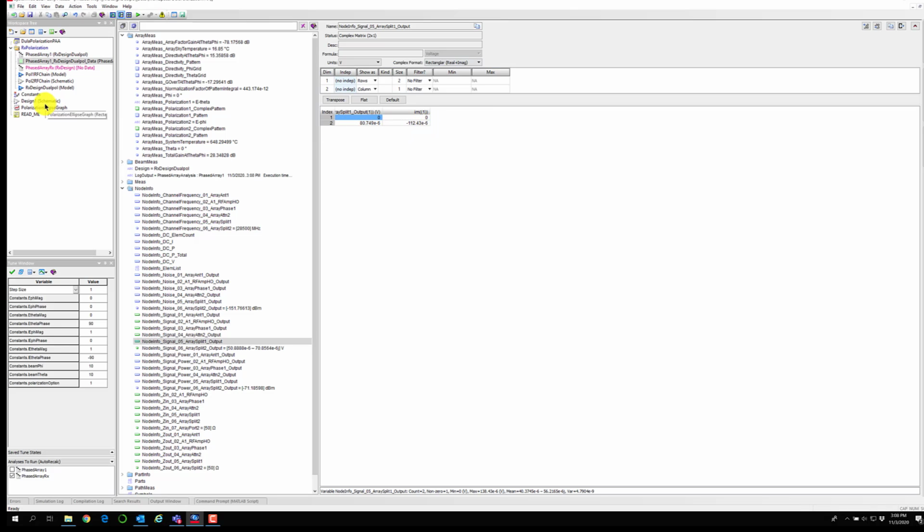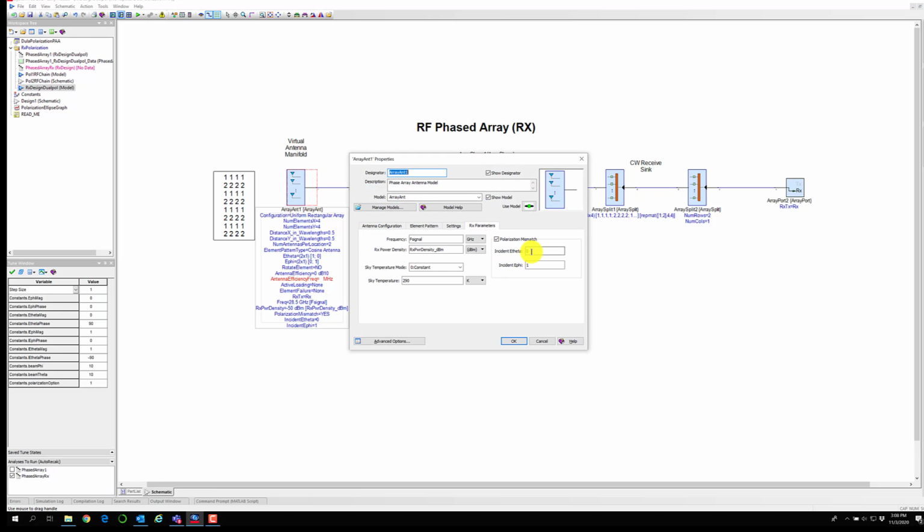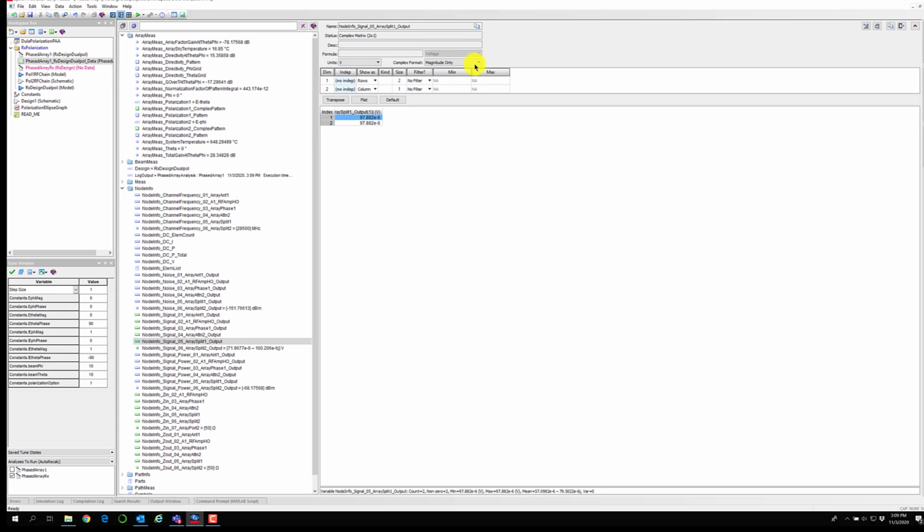What if my incoming wave has both the polarizations? Will these antennas react to that? Let's examine that as well. Let's say both polarizations are equally contributing to the signal. Now, if we simulate again and watch, we get outputs on both the antennas. So clearly you can use this polarization discrimination to your advantage, taking advantage of the polarization diversity in your communication system.